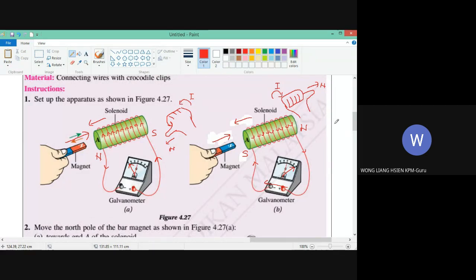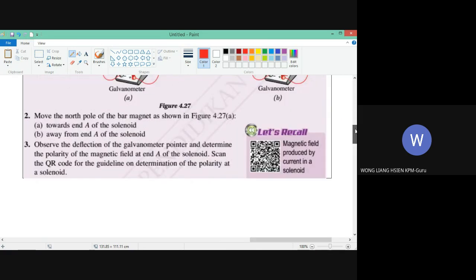So you will feel an opposing force, so you need to produce extra energy to overcome that opposing force. Then that extra energy that you use to overcome the opposing force will convert into electrical energy. That is where the electrical energy comes from: from a part of the force that you use to produce the relative motion, to produce the cutting effect.